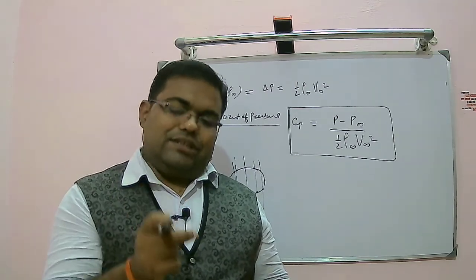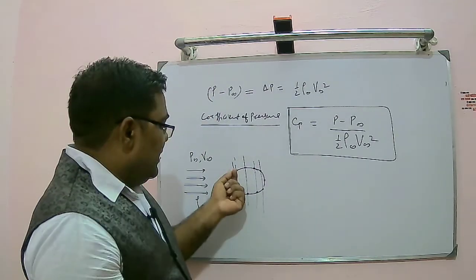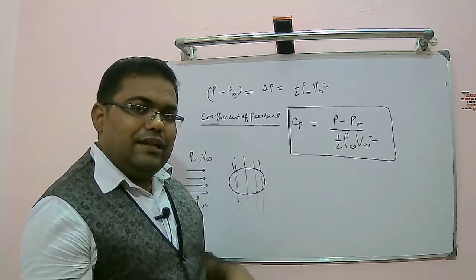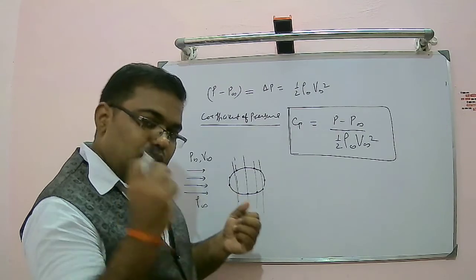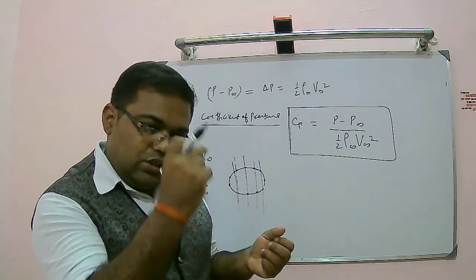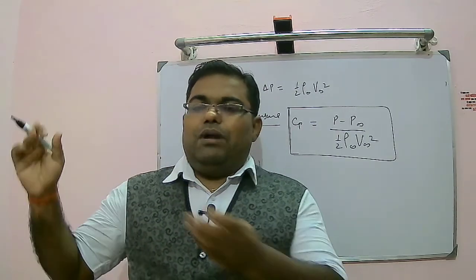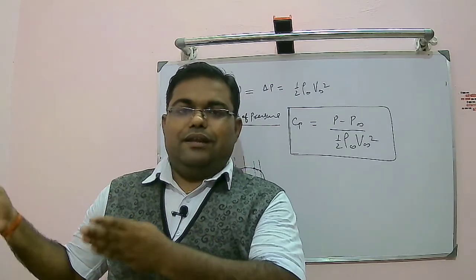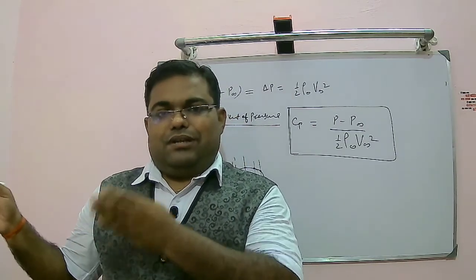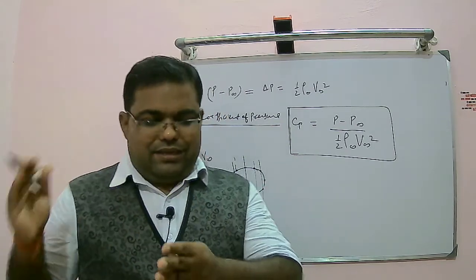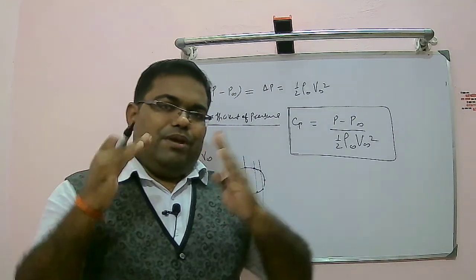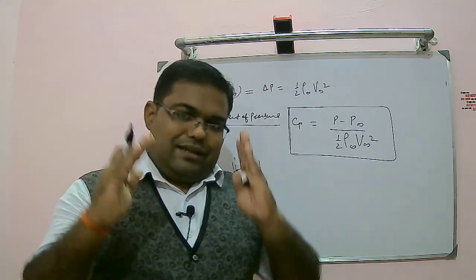Ports are nothing but a tube kind of structure that will suck the air. So when air is coming and travels over the surface, through these ports, these holes, air will go inside, and that tubing will be connected to the multi-bank manometer. At each location we measure the pressure, and by taking atmospheric pressure as a reference, we find out the pressure coefficient at different locations.